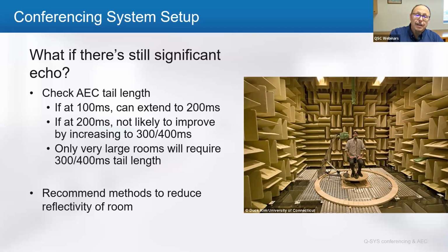But we do have a planning clocking domains deep dive webinar. I think we'll be giving one of those in July, Chris. So if you want to make sure that you've got your boundary clocks set up right and how to move that. I noticed in here, you're using a Core 510 with a card. One of the benefits of software-based Dante is that the core itself can be the boundary clock. So anyways, I recommend tuning in for that. But yeah, you shouldn't have any serious time alignment issues, whether you're using a hardware-based Dante solution or a software-based Dante.